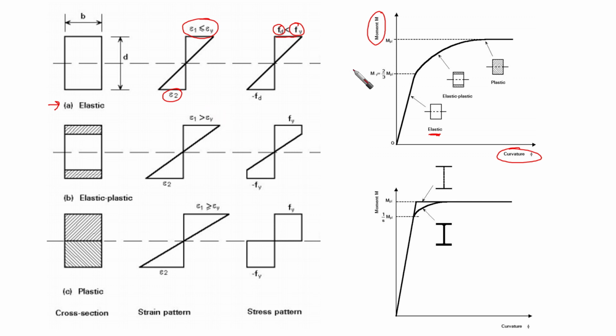What is the meaning of yield stress and yield strain here? It is similar to yield moment. And if we have the curvature, phi for example, then it is phi yield, corresponding to yield. So whatever we have here in the elastic range, we call it elastic, and the shape of the stresses is distributed linearly, as you can see here.